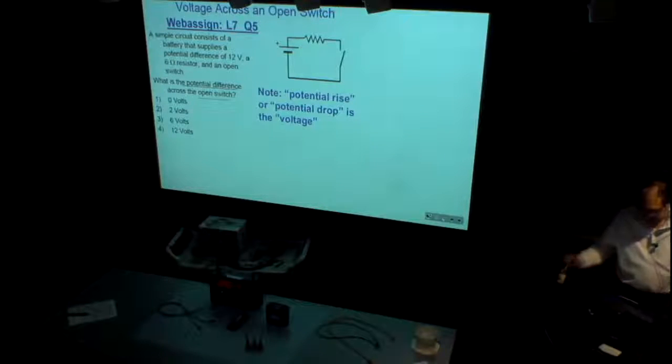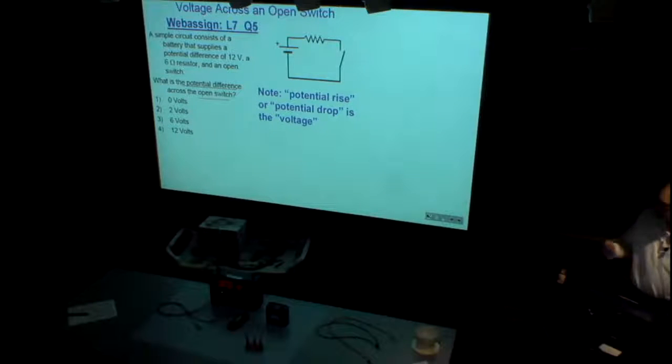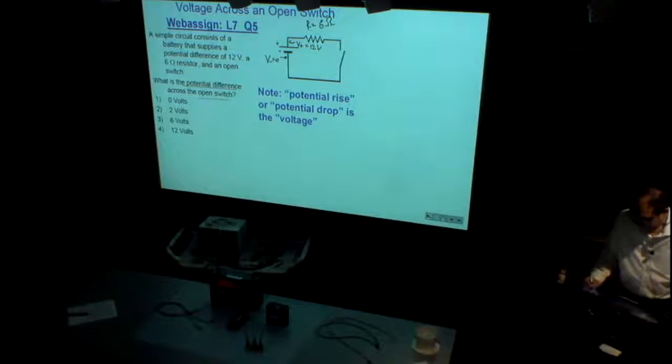Now, to reason through, you have to use the knowledge that a wire does not change potential. So electric potential here, we always set it to 0. We don't have to, it's just easier. So electric potential here will be equal to 12 volts. This resistor R has the resistance of 6 ohms. So Ohm's law, which relates the voltage, current, and resistance, tells us that electric current through the resistor should be equal to 12 over 6, 2 amps.